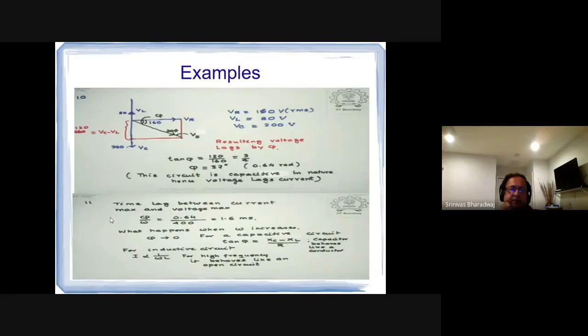So remember those formulas, and remember to learn to manipulate these almost like linear circuits, almost like resistive circuits. You write the capacitance like this and write the resistance like this, therefore using minus j by omega C for the capacitor and j omega L for the inductor. Then you just do resistive circuit manipulation, and you will end up with Z. Then you calculate the Z, and then you calculate V equals IR. This is how you solve examples involving circuits.